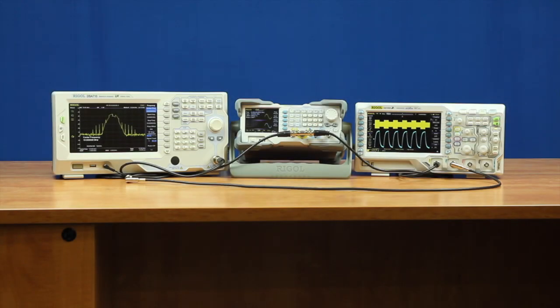So in the last example, we were transmitting and demodulating analog data. Here, let's look at a similar modulation, but with digital data. So this is an amplitude shift key, which is in essence an amplitude modulation where there are only two values, a high amplitude and a low amplitude, that are equivalent to a 0 and a 1.